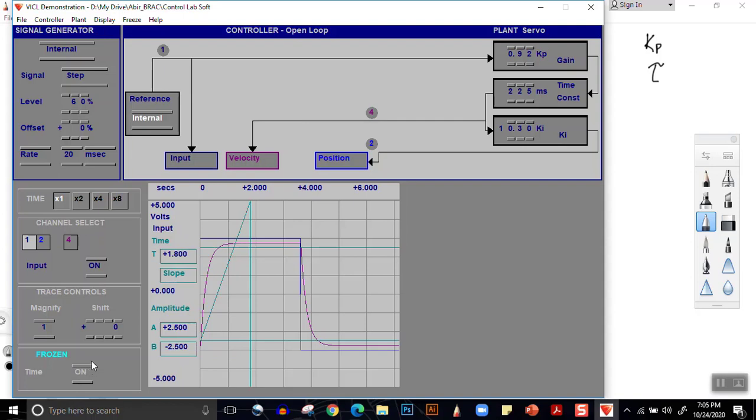If we turn on, you can see here the amplitude A. Now we click this 2.5 portion, and we click here, and we align with the input, and for B, we click here and it aligns with the negative part of the input. So this plus 3 minus 3, that is, there is a difference of 6 volts.